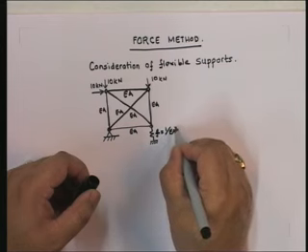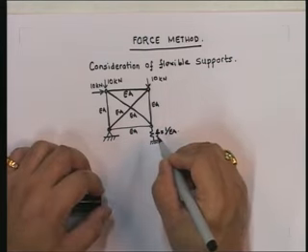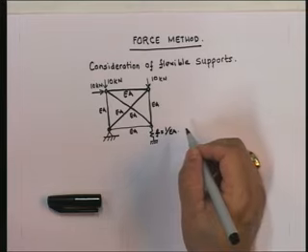Because if you considered the axial deformation of the pier, then the pier becomes actually flexible, and since the pier is essentially subjected to vertical axial forces, because that is how the load is transferred through the pier, we are now considering the pier to be deformable, and what we are saying in this particular case is that the pier flexibility is given as 1 upon EA. That is all that we are saying.